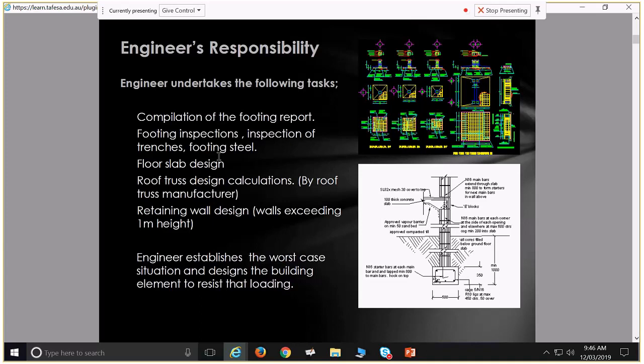The ramifications of footings going wrong are also incredibly expensive. It's the sort of thing you want to be insured for. So, given that the footings are so important in terms of their design, it's also very important for the engineer to inspect those trenches and the installation of the steel whenever they're being installed. So they're going to want to have notice for when the trench is going to be dug and the steel work is in place, and they'll want to see that before it gets poured. Possibly they'll even want to be on the site on the morning it gets poured.